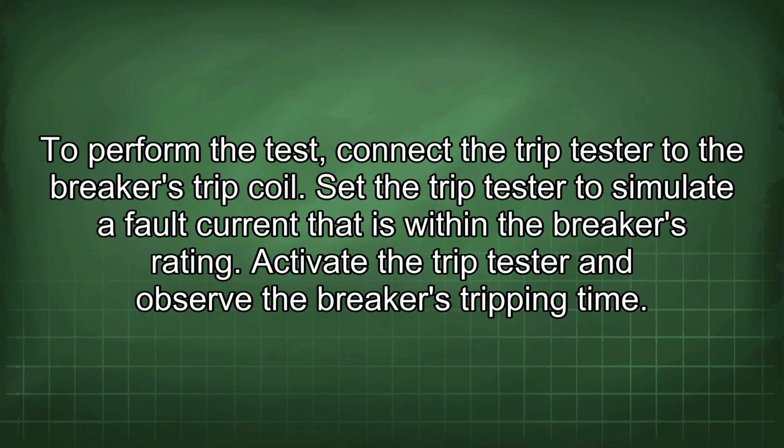To perform the test, connect the trip tester to the breaker's trip coil. Set the trip tester to simulate a fault current that is within the breaker's rating.